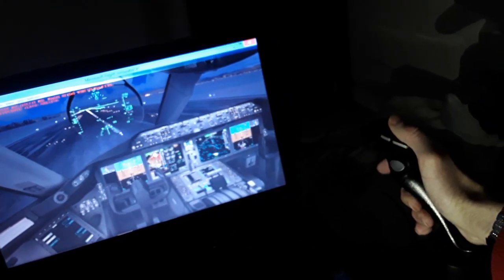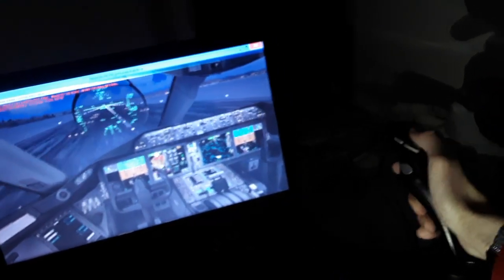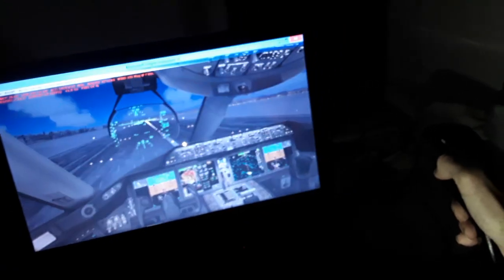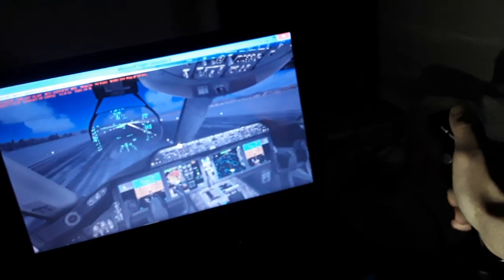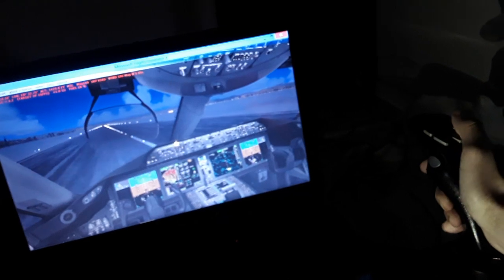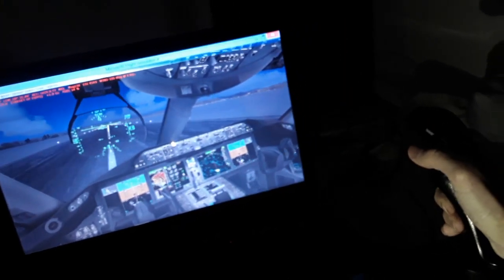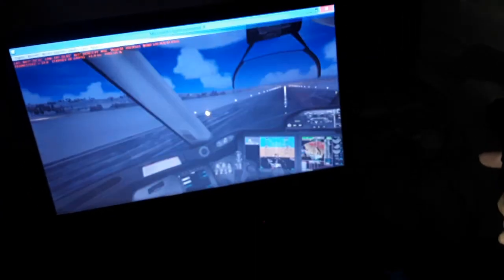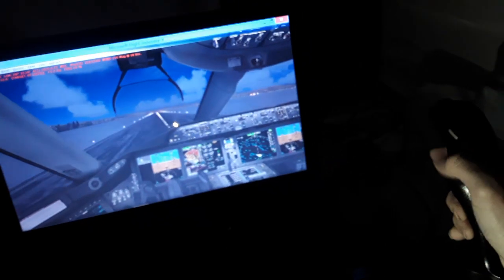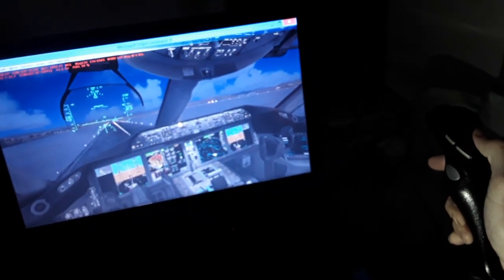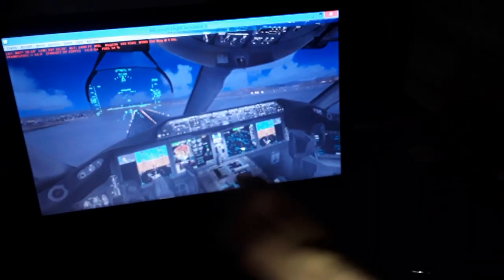So we press the yoke down until 80 knots and align with the rudder pedals. So we have 90 knots, 100, 120, 130. So we have V1. We rotate over here, we rotate like 9 degrees. It's 9 degrees up. So we have the positive rate of climb.